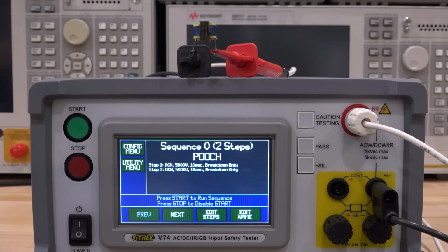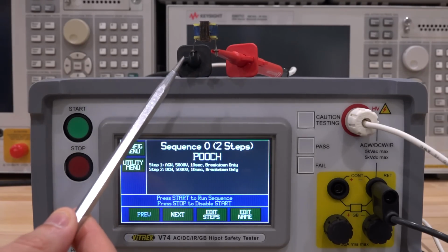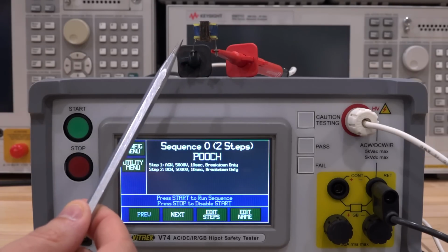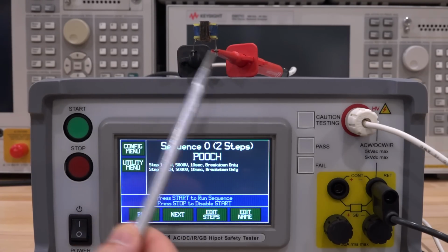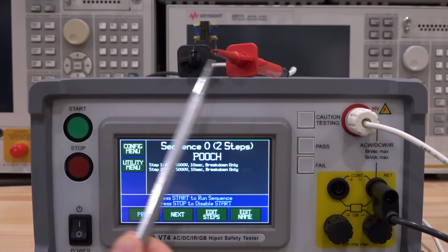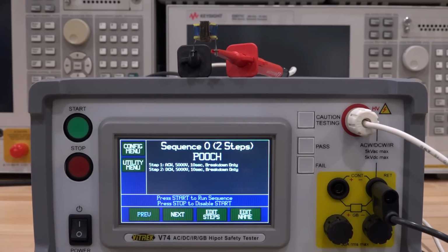So now let's try to stress test something that was never intended to operate with 5,000 volts across it. Here I have a tiny little audio transformer, and this transformer has its primary terminals shorted together and a secondary terminal shorted together. We're going to apply 5,000 volts across that, which means that a strong electric field will be present between the primary and the secondary coils, and it has to be able to take that strong field up to 15,000 volt peak to peak or so. Here we go.